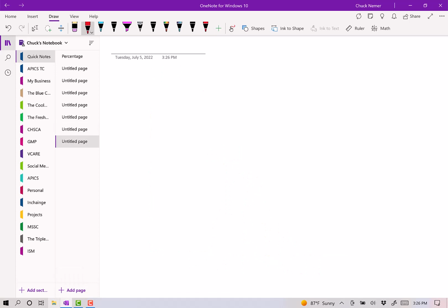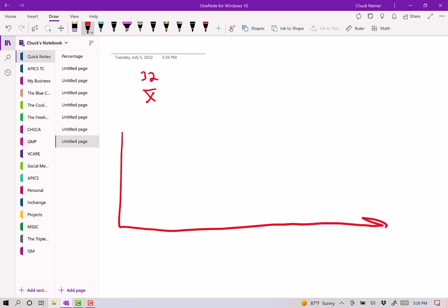Control chart has us taking a sample of parts. Let's say we grab 32 parts out of a box of 10,000 fasteners, and we measure the length, and we figure out the average, the mathematical mean, and what we do is we plot that over time. So this is time down here. We plot what the length of that part is. Now what we also calculate, and so the sample of 32 pieces might be the average is 1.05 inches.